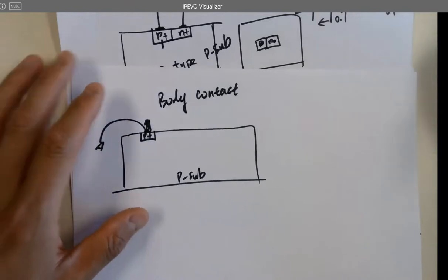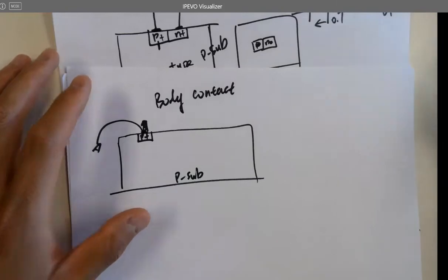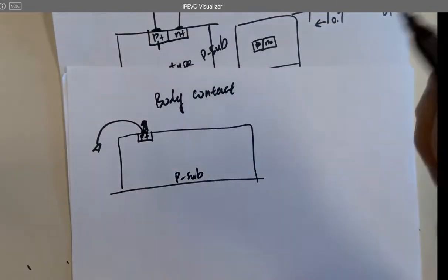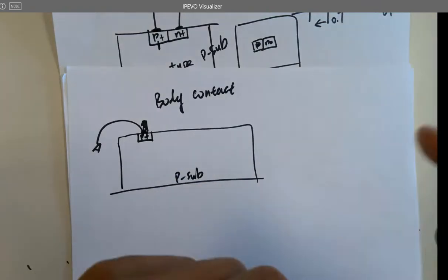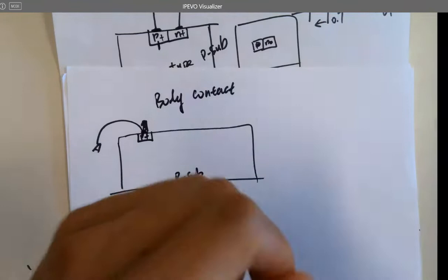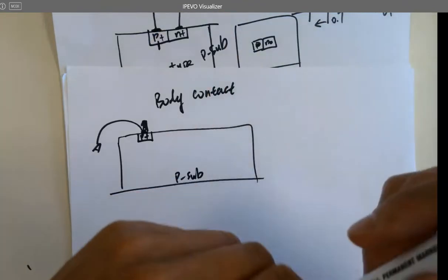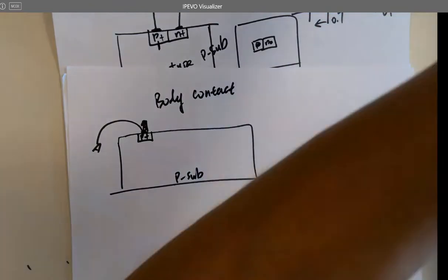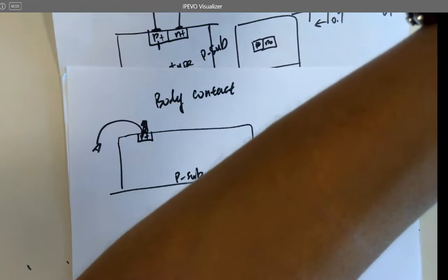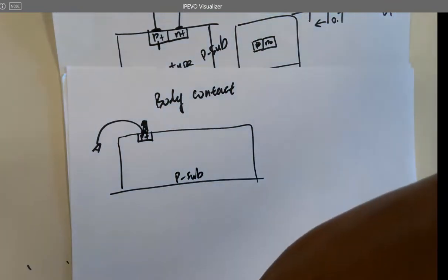In order to answer that question, because we have received all the chips from Moses, who is not doing this anymore, many years ago in my analog class, my senior son last year was trying to figure it out. I was trying to answer whether they have a conductive epoxy, because we received all the dies and purchased all the packages, right? The next step is to put the die into the package and do the wire bonding. Otherwise, you have to purchase the epoxy.